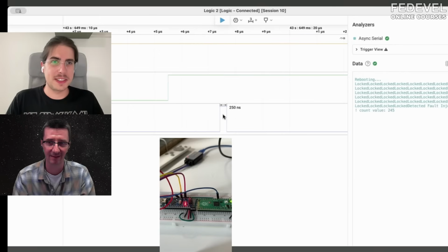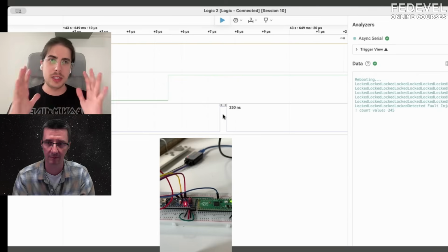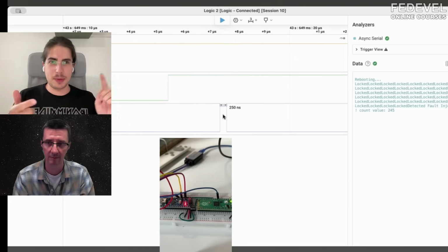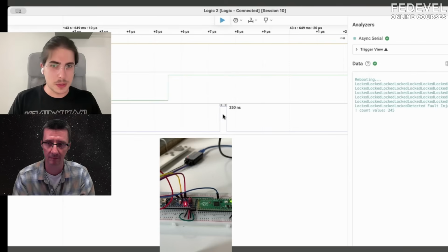For board engineering, of course, we know about capacitance, decoupling capacitors. These can actually be a problem sometimes because they can hold so much charge that you need to make a really wide pulse for the chip to recognize it. And if you make it too wide, then your peripherals are going to die, because other parts of the chip are going to lose power: registers, RAM, caches, all of that. If they lose too much energy for too much time, they will cause bit flips and errors, and the target will just crash.